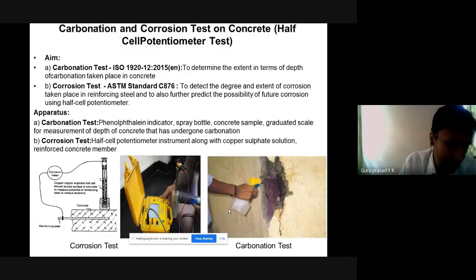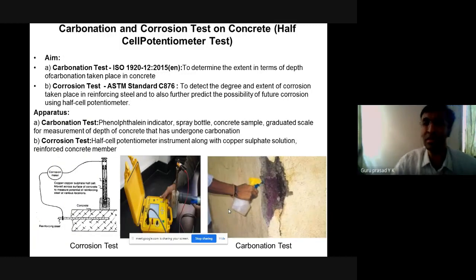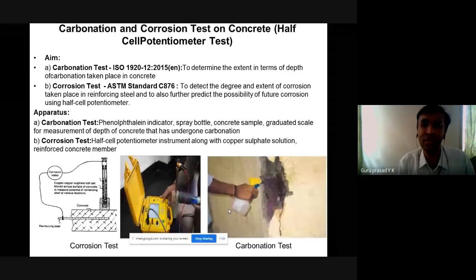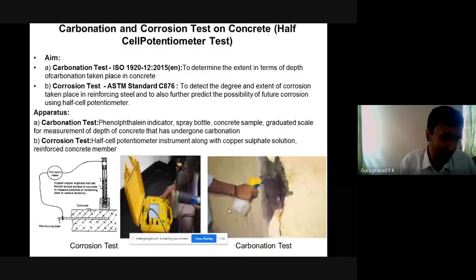In most cases, people don't know this. When they go to use the probes, they drop them from a certain height because of handling issues, and when it falls down, the piezoelectric crystal inside cracks and they are not aware of it. Suddenly it starts giving you frivolous values, or it may not work at all. Usually it will not work.